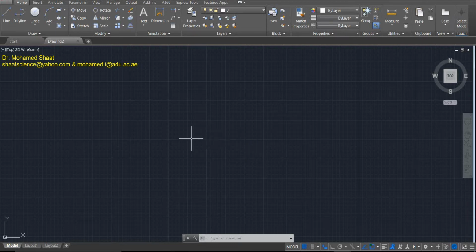So as we discussed, starting with the first part, which is the properties, as we discussed at the start of this course, it is highly important to achieve some contrast in the different objects that we are using, or the different types of lines. We discussed different types of lines. We said that we do have a visible line, we do have a dashed line that represents any hidden edges in an object. We discussed the center line, the chain line. We discussed even the line that would be used for adding dimensions.